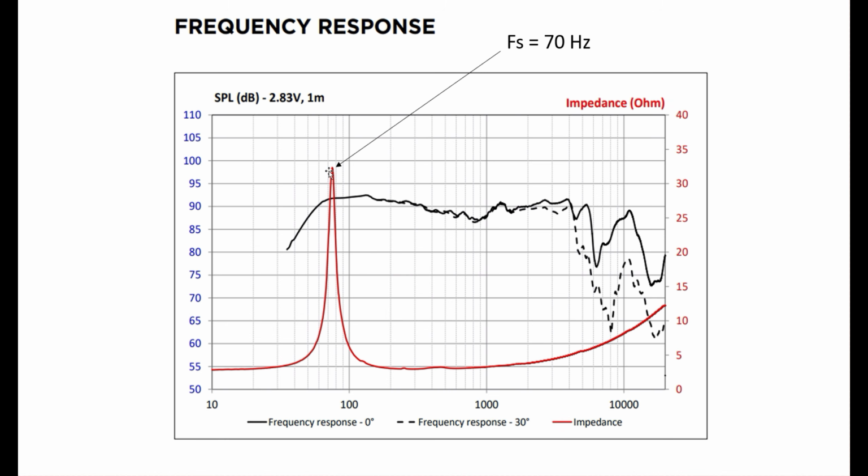That electrical damping that occurs, because the cone is moving at its greatest excursion. Therefore, the voice coil is moving through the magnet with its greatest pitch, for want of a better term. That's probably not the right term, but it's creating the biggest electrical back EMF force, right? And so you get this big peak in the impedance curve. I think that's how it works.